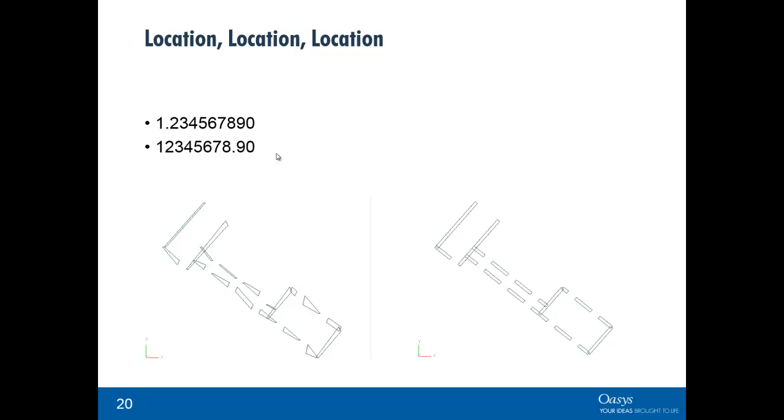And this is a model we received a couple of weeks ago when the graphics were looking quite screwy down the left hand side there, and it was about 100,000 kilometers away from the origin. Move the model to the origin or close to the origin, and lo and behold, the graphics work well. So if you're getting a model which is looking strange like that, it's quite possibly the location in space.